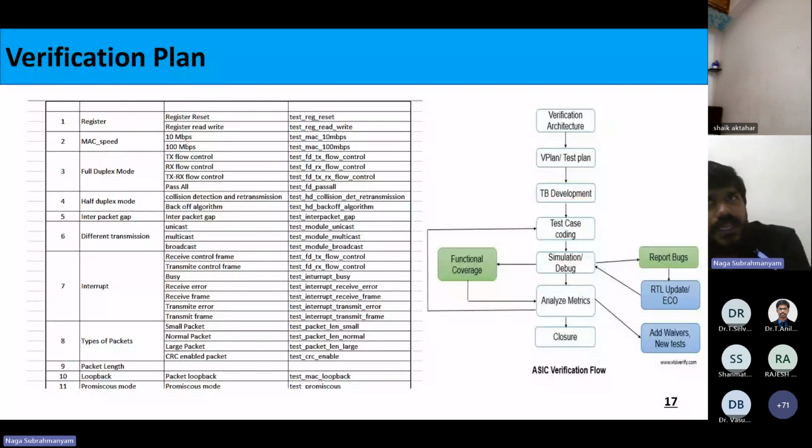It means in the state machine, half duplex mode will be enabled, so that your entire Ethernet will behave in half duplex mode. So now from my verification environment, I will prepare the data 200 and put it in the mode register.